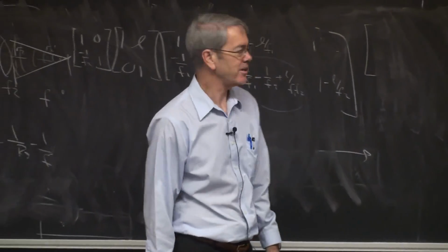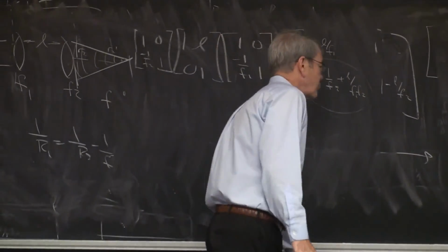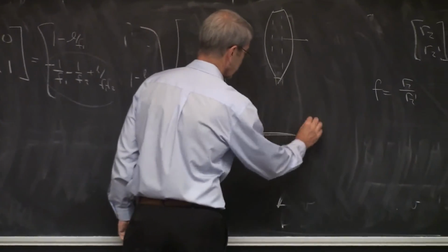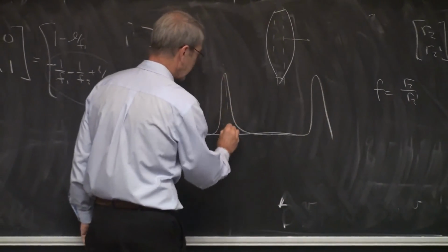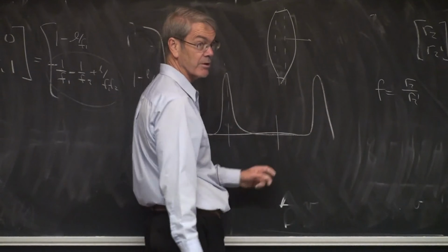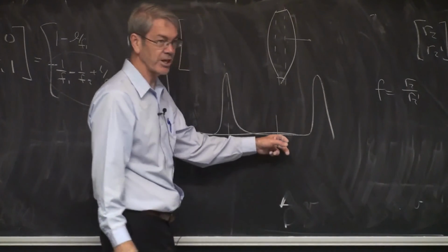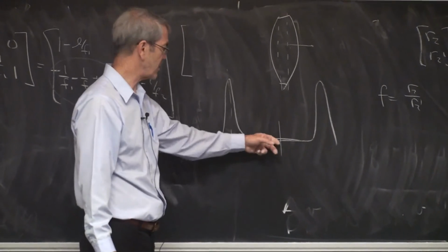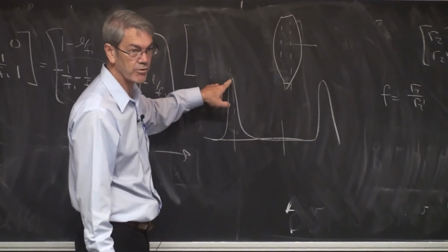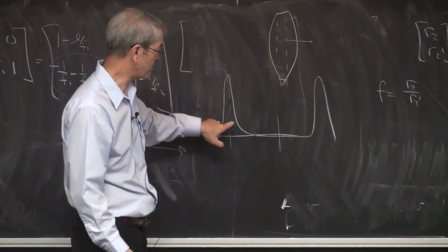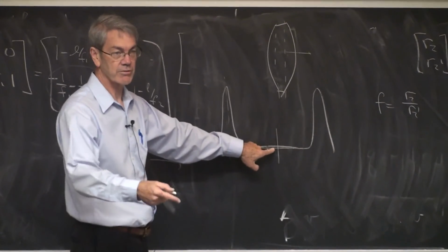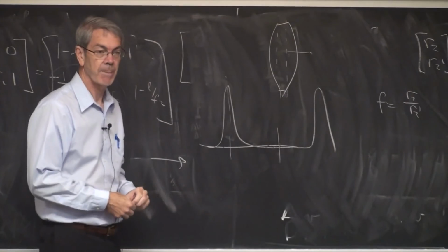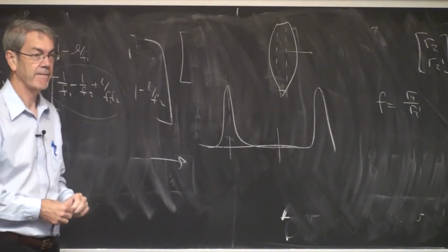I guess I'd say, the optimal: I'd want one transmitting here, and one right there in the middle. That'd be the maximum rejection and the maximum transmission. So that's what I'd look for. Here, you just set one frequency to Q times FSR, another to Q plus a half times that FSR. FSR is not in any of the chapters of the book, I think.